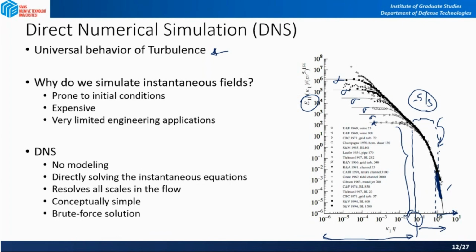But if you collect the DNS data, since you have correct instantaneous fluctuations, and if you, let's say, have enough hard disk space, and you can collect enough number of instantaneous data, you can get real turbulent kinetic energy distribution. And then compare with the RANS, and if there is any fine tuning that you can do on the RANS type turbulence models, then you can do and correct that.